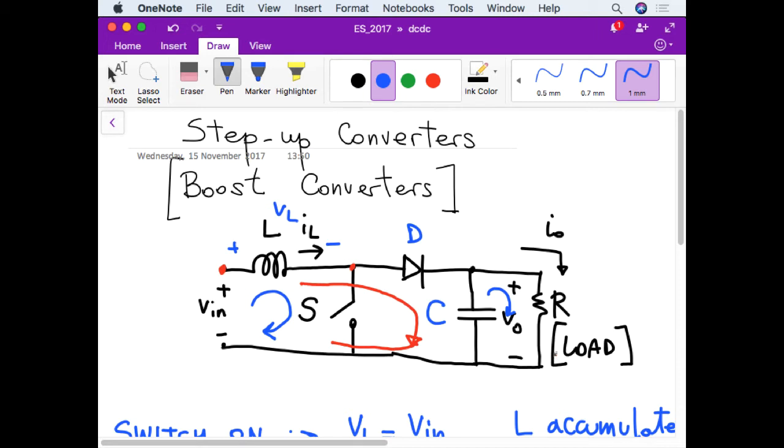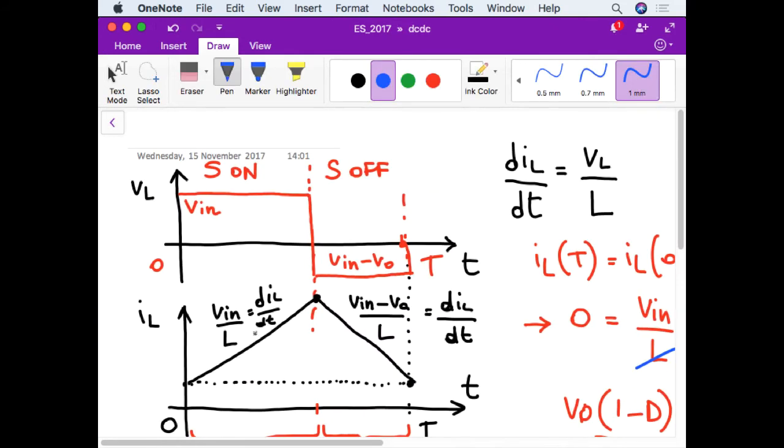And this, of course, has an effect, because if we reduce the current absorbed by the load, we reduce the average current through the inductor, and therefore, let me go here, we move down this line.